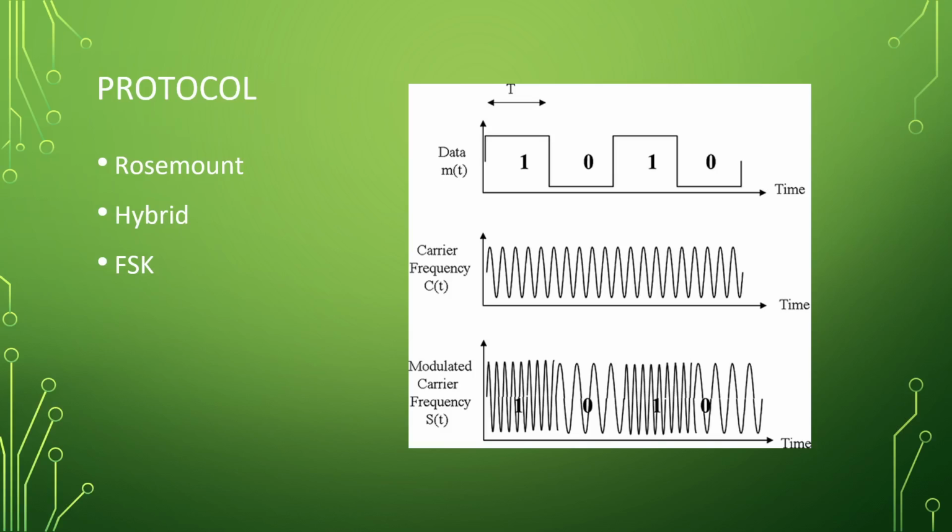This is considered to be an open standard, and it's a hybrid. It reuses the 4 to 20 milliamp instrumentation cabling, so this is truly designed to update those old analog sensors. It's like, oh, we already have these analog sensors out there. We need some better technology, or we just need to replace the sensor. HART is kind of trying to put its foot in the door, saying, you want to use us. You don't want to just put another one of those boring old sensors in. You want our fancy sensor and all the other wonderful things.